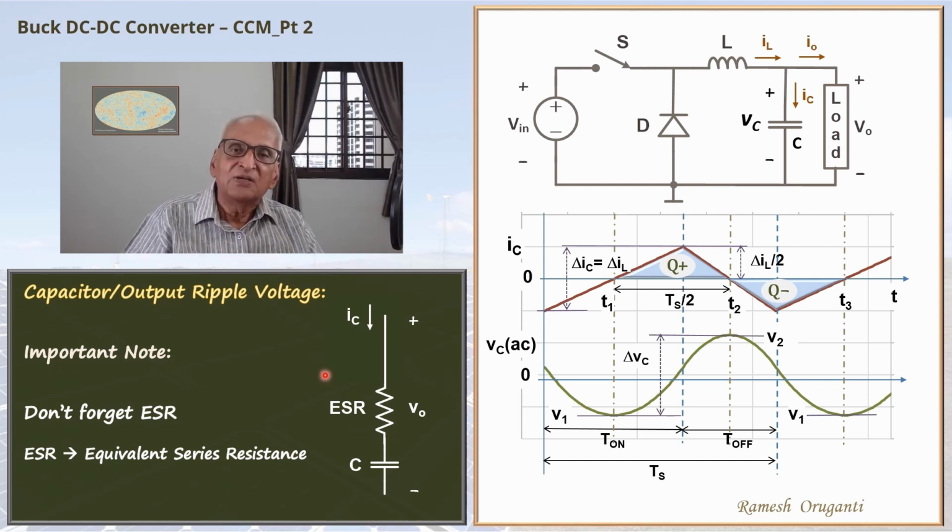You may ask, capacitors have leakage associated with them that can be represented by a parallel resistance. What about that? Such a parasitic resistor in parallel with the capacitor may not be an issue because the load is also parallel to the capacitor. So it will just get added up with the load. It might have a small effect on the load, especially under no load conditions.